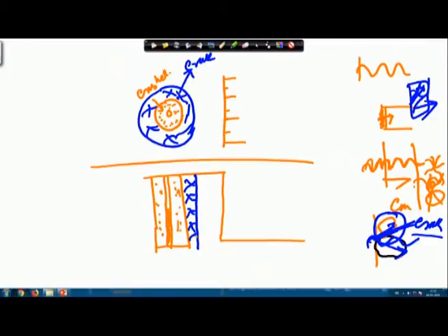So, this cracked zone will be there, but the wave is still propagating, and what will happen? We will find that the wave is no longer strong enough to fail the rock even under compression. That means, though differential motions are there, it is not strong enough to fail the rock under shear, because the shear strength is a little bit higher than that. But still the wave is propagating.